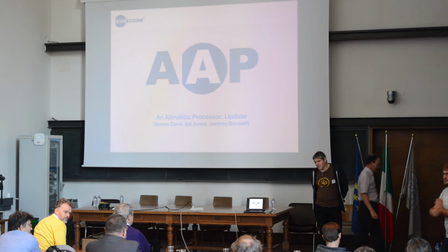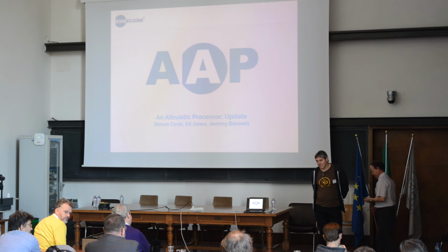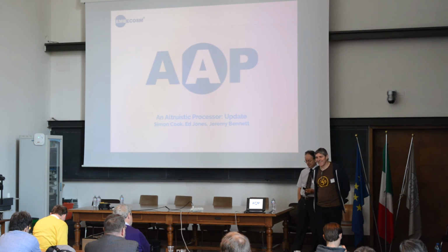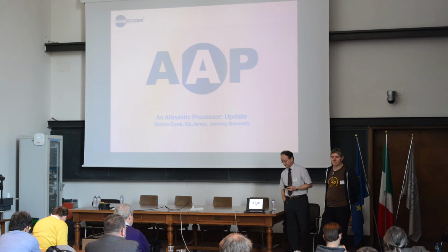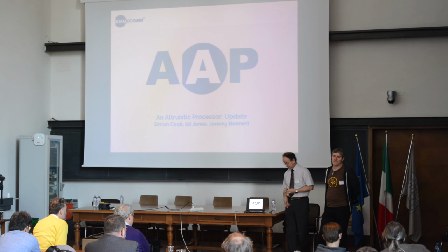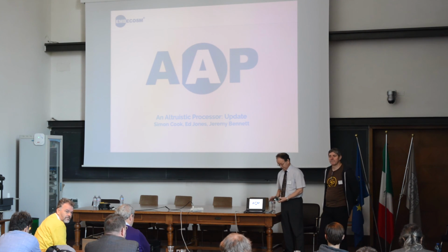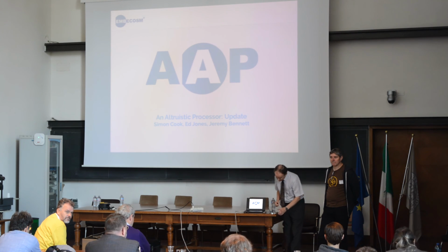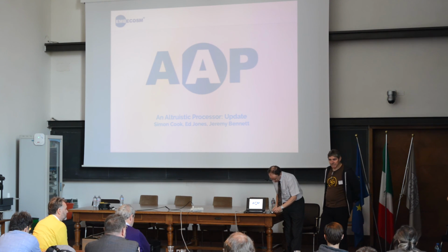You know, having spent a whole lecture yesterday talking on how every LUT is precious, that's a small number of 4 LUTs, and I'm real used to 6 LUTs. One of the real uses that I would see for a small board like this, you already brought it out, is robotics and robotics controllers. A robotics controller really needs to be a tight real-time system. You can build that with your own CPU, such as the ZIP CPU, nicely inside of an FPGA.